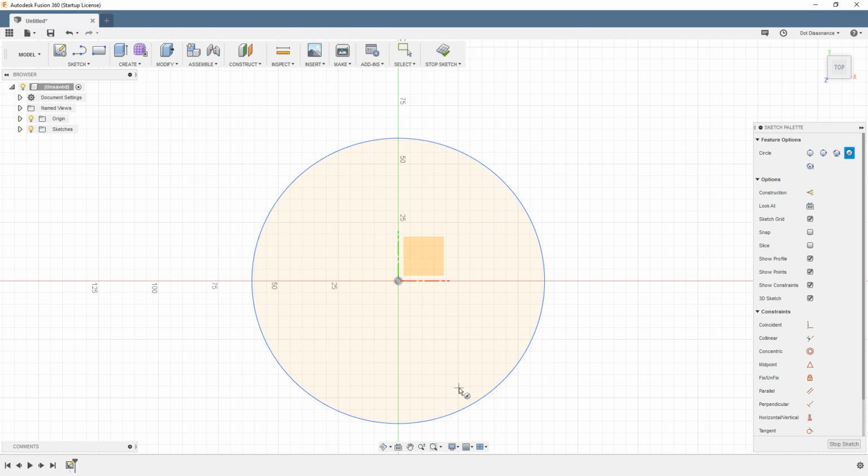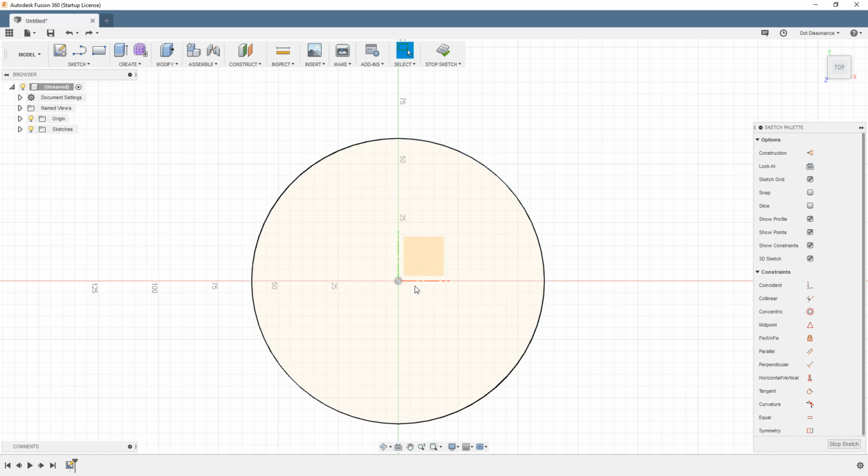So I click here, and I have now a sketch. By the way, just to tell you what I was doing here, if you're used to graphic type programs, you're not clicking and holding and dragging. You're clicking once for a point, in this case it's a center point, and then you let go of the left button, you bring it out, and then you click again, you see? Control Z, by the way, is undo. So click center, let go, bring it out, click, finish.